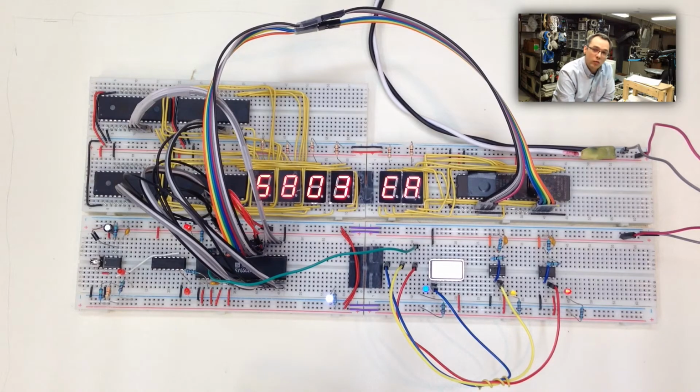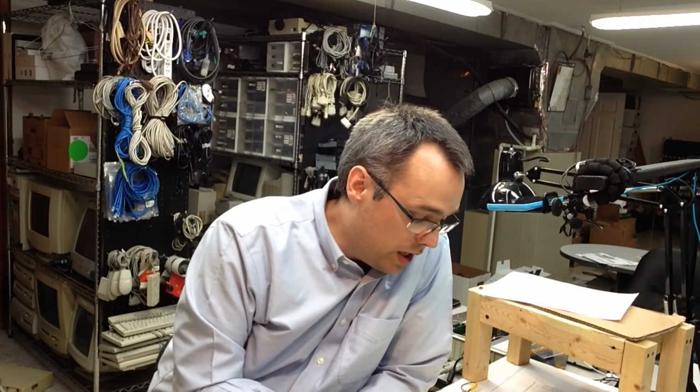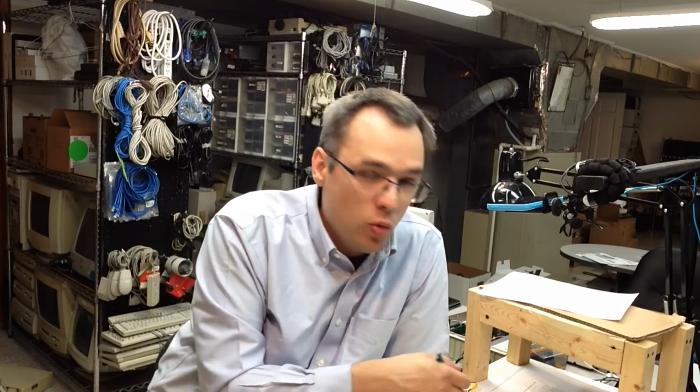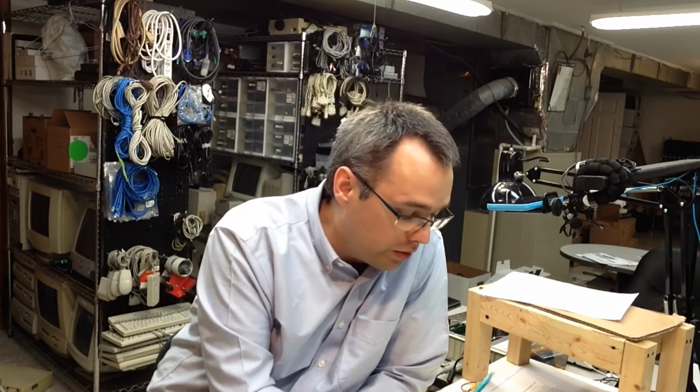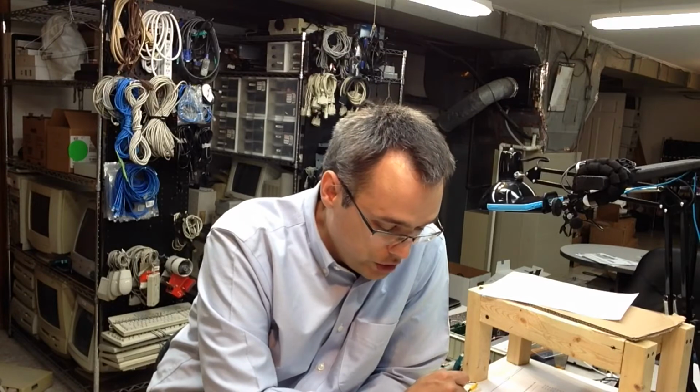We have a good power on reset circuit so that when we get this up to speed and connected to an actual high-speed oscillator, it will auto reset and start executing from the right location. And we have everything basically set up and ready to go for the next step. That next step, I'm pretty sure, is going to be connecting some ROM up to the computer to give it something to execute. Not sure what we're going to have it do yet because I don't really have any input or output out of the machine, but maybe we'll just have it spin in a loop for a while.